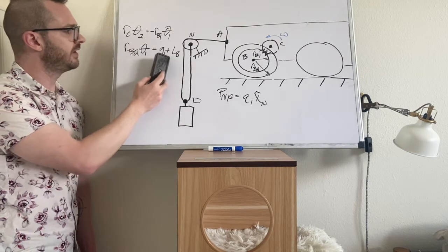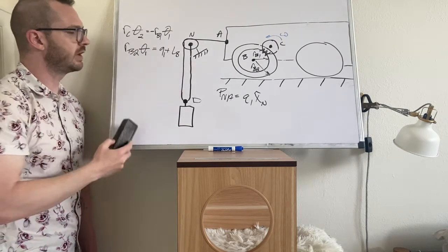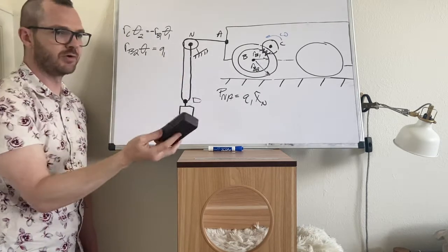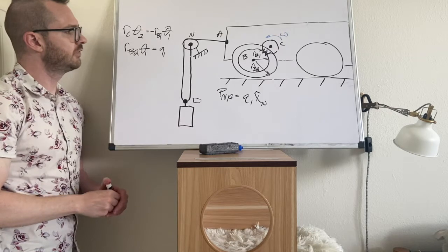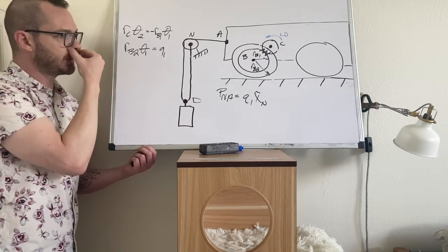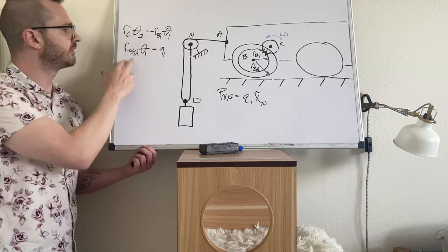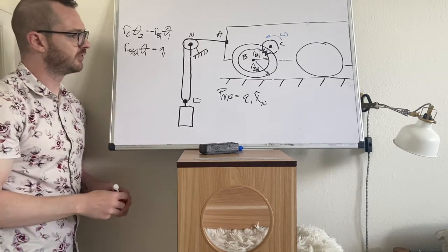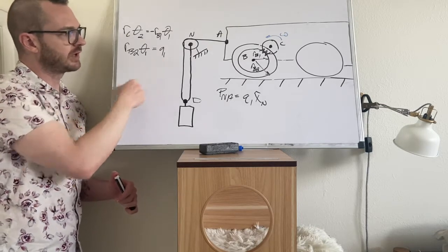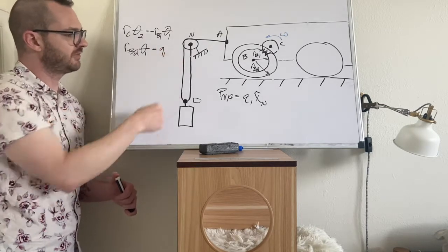And any offset that you add to this equation, as soon as you take the derivative, those offsets are going to go to 0 anyway. So when you're writing these constraint equations, you can keep in mind that we're eventually going to take the derivatives of them. Now, in this case, this constraint works just as well without that particular offset.